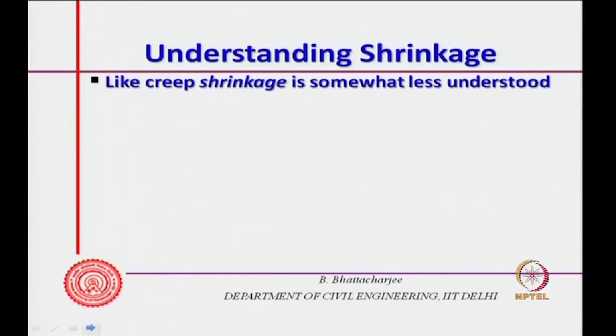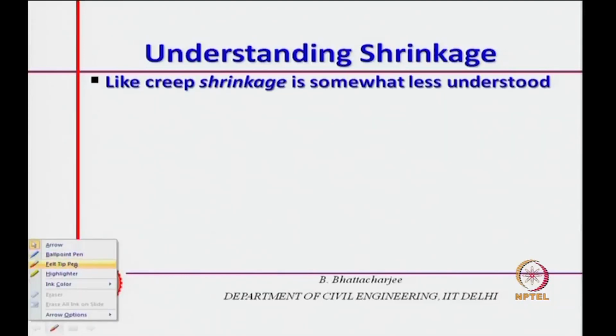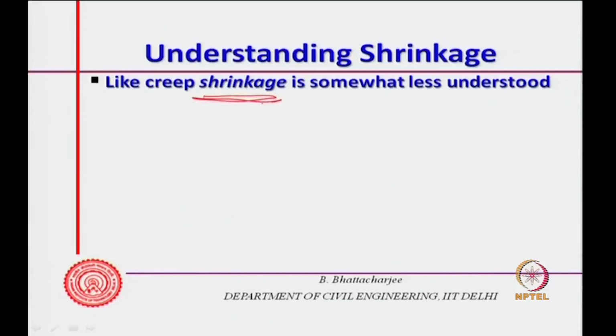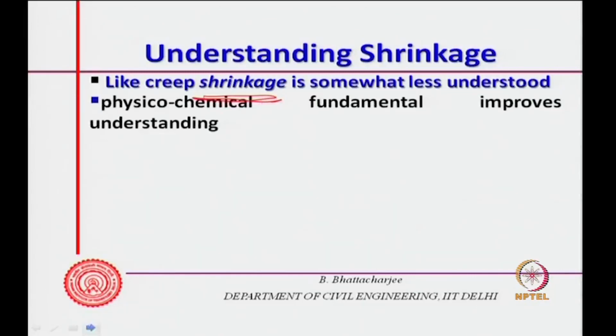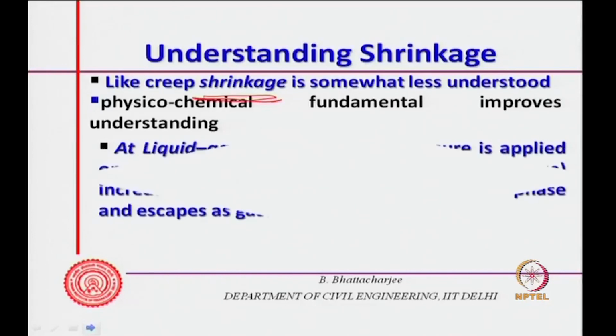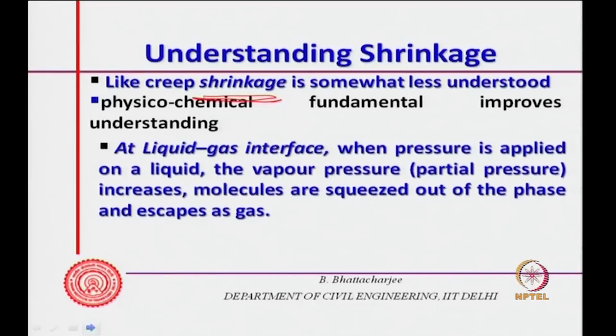Now, like creep, shrinkage is somewhat less understood, it is not fully understood. Shrinkage issues in concrete are relatively less understood. Of course, if we want to understand it more, then we must look into the physico-chemical fundamentals, and that is what we are trying to do right now. Now, to start that, we must understand what happens at a liquid-gas interface.